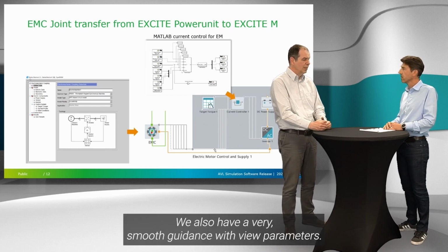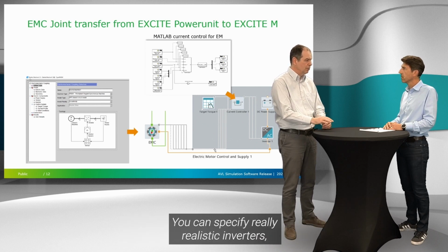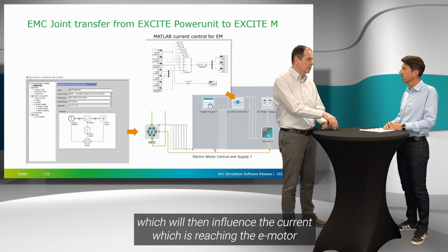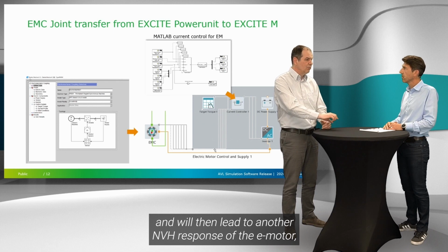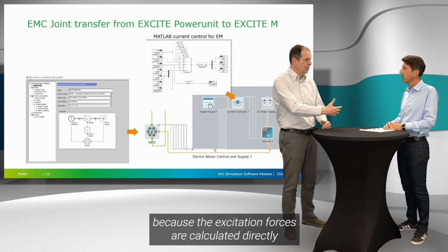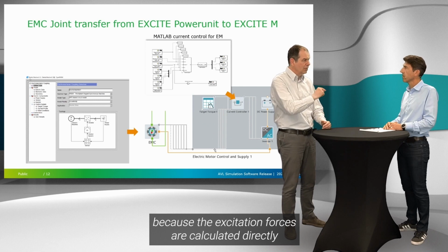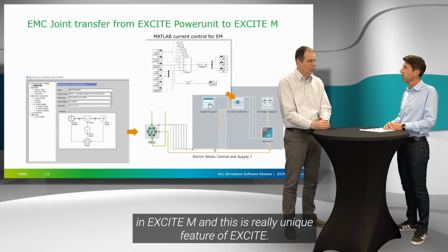We also have a very smooth guidance with view parameters. You can specify really realistic inverters, which will then influence the current reaching the e-motor, or this e-motor joint in EXCITE, and will then lead to another NVH response of the e-motor, because the excitation forces are calculated directly in EXCITE, and this is a really unique feature of EXCITE.